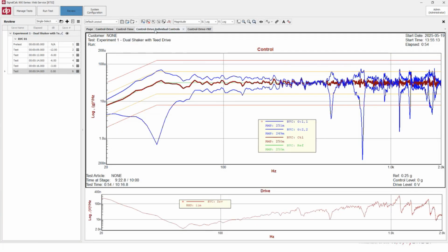And let's take a look at the control channel deviation. So we saw at low frequency, below resonances, we had differences in the amplifiers that were causing some control deviations. Now, after the first resonance, you can see that the control channels never converge, never identical, except for some places where they kind of switch between one being higher and one being lower.